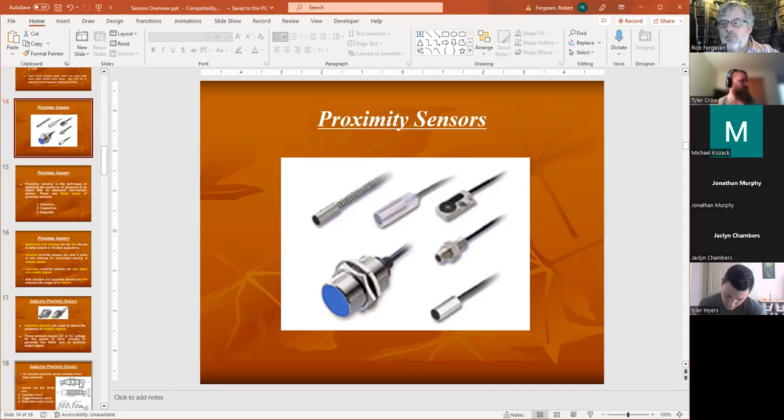If you're in the industry, a prox switch is any switch that lets you be nearby your target without touching your target. So that automatically gives you some advantages if you have something you can be nearby to without touching it. Now you have no moving parts. So your mean time between failure, even though it was good with a robust limit switch, can go much, much longer. Now the only thing that can kill you is EMI or some sort of lightning strike. All right, so your prox switches can go a lot longer.